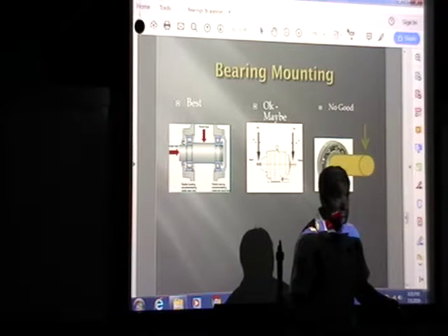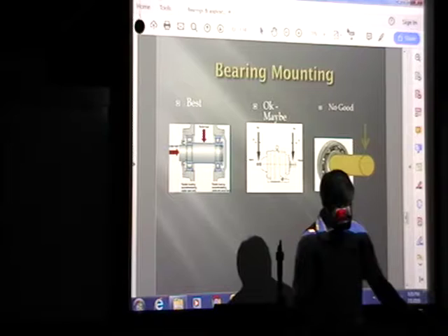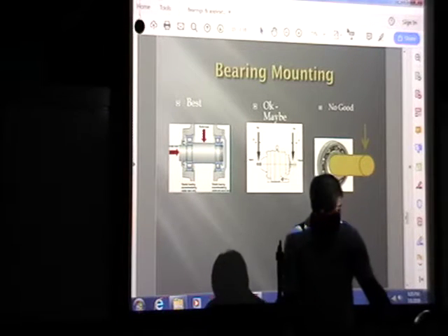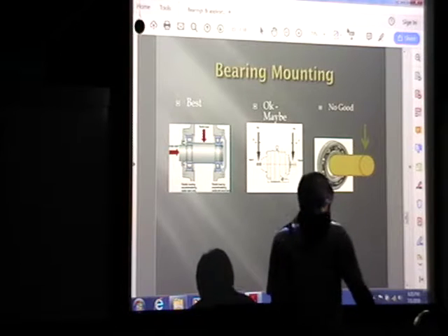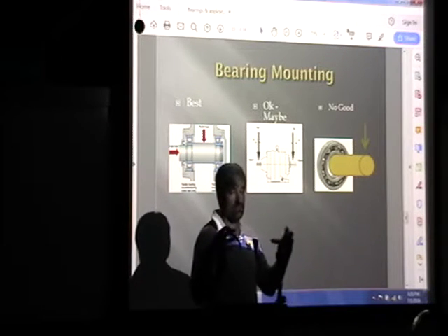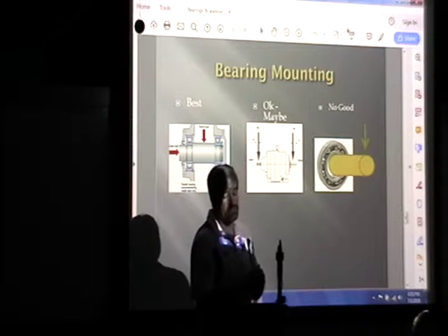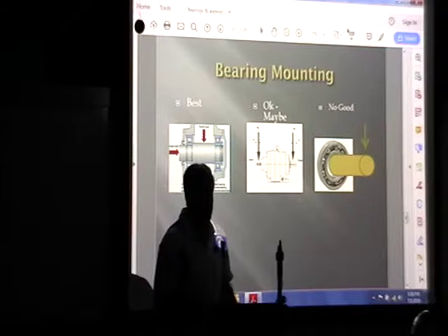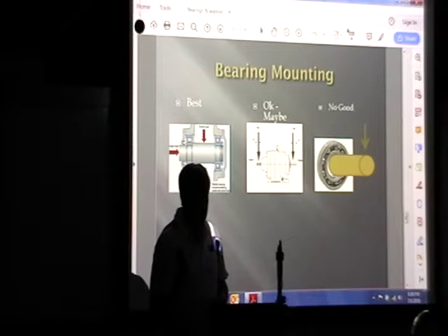The bearings themselves are just going to lock right up. There are different degrees to that, but one of the things I've seen in the robotics world a lot, because you guys just aren't aware of how much your shafts are deflecting or how much alignment needs to take place in the bearing sets, is you're losing a lot of your power in your motors because the bearings themselves are eating it up with friction and binding.